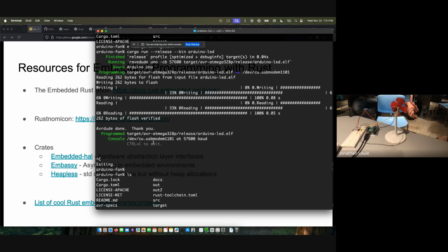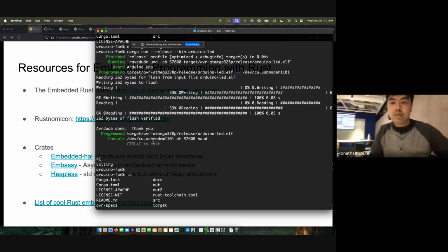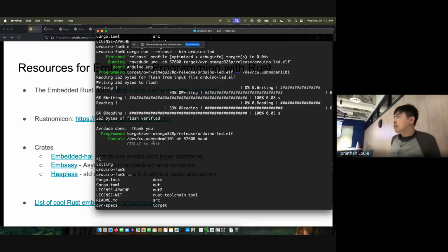And you are able to look into it, and you can see consoles on your laptop that are showing you this. Yeah. So depending on the exact one, there will often be some specific software that comes along with it too. There's a protocol called JTAG. It's fairly slow, but it shifts all the register values out so that you can see all of the internal register values, for example. And that goes back to the assembly level. You can actually look to see what's in each register.